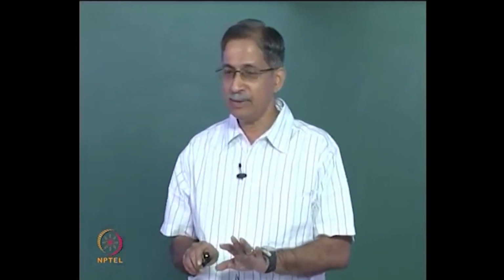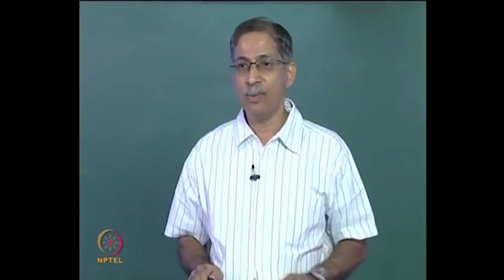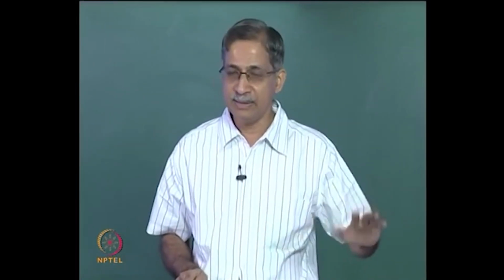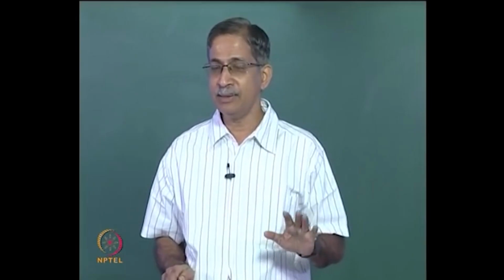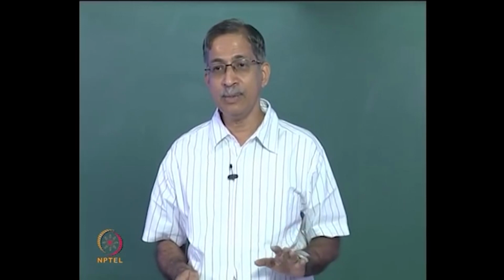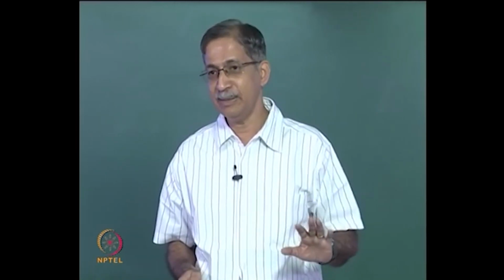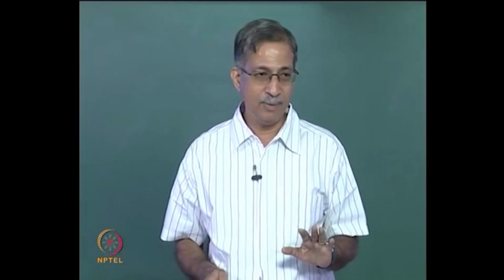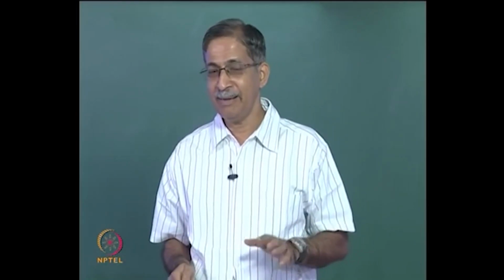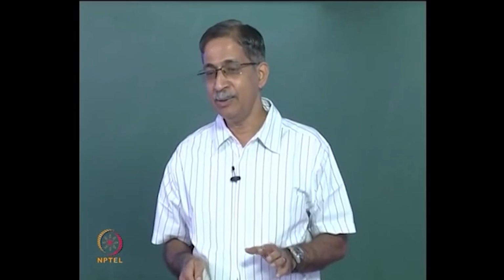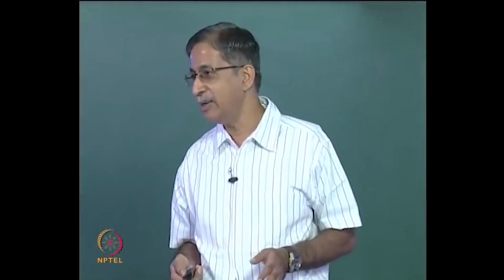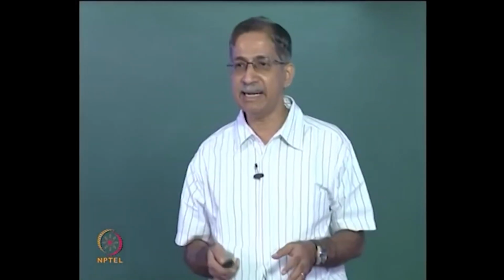Is it clear? So we are going to explore these two approaches. One is an energy approach where you minimize complementary strain energy, but mind you, the theorem of least work is strictly applicable only when you do not have support settlements, only when you have dj equal to 0. But if you had support settlements, you could still invoke the energy method, but you are basically doing method of consistent deformations, you are just finding displacements using an energy formulation.